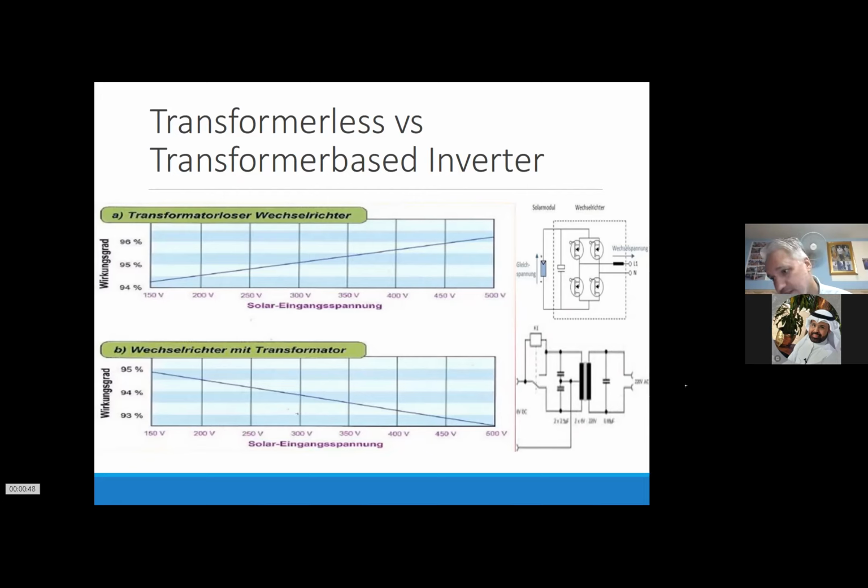If you are, as said, too hot in summertime, and you only reach 500 or 450 or even 400 volt, yes, the inverter can do that. It's got a big window right now, but the efficiency is going down. So that's the problem in summertime with some modules. They suffer in combination with the inverter. And that's how you can control it. Like I said, with a binning or with the string, you can check what the modules actually want.